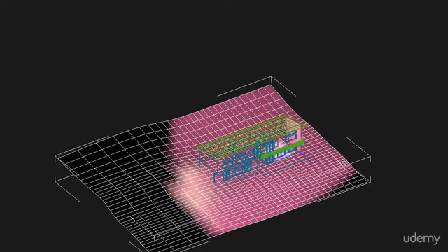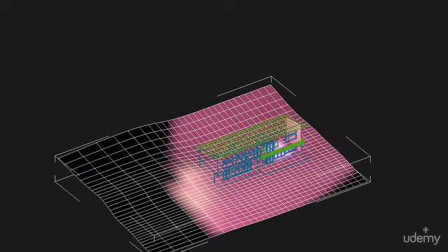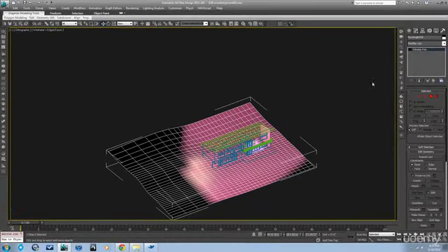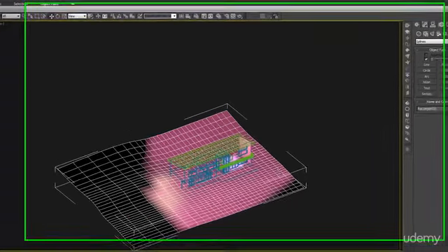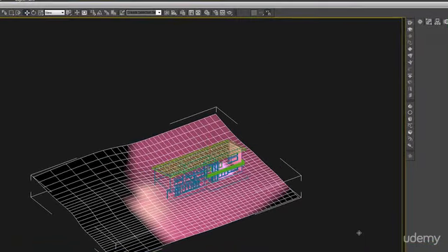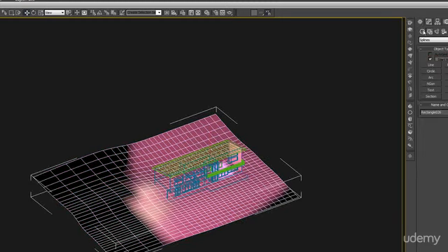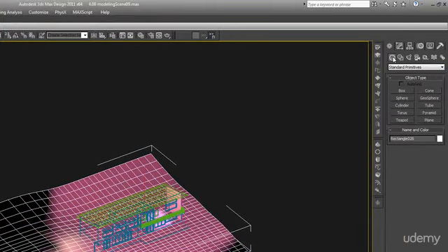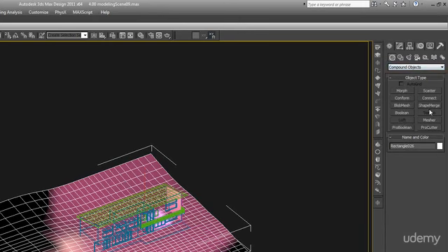If we take this and let's just collapse it down by converting it to edit poly again. That burns in that Turbo Smooth. And if we take that, actually, let's convert it to edit mesh. It'll look exactly the same. Go to create, objects, compound objects, shape merge.